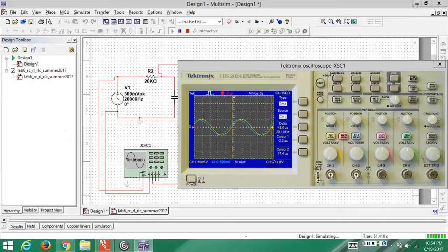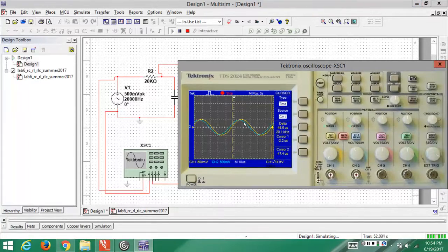So if I go back now, I need to find del t from this waveform. When I'm on the channel 1 yellow waveform, let's use one of these differences over here. Let's select the cursor again and move it.